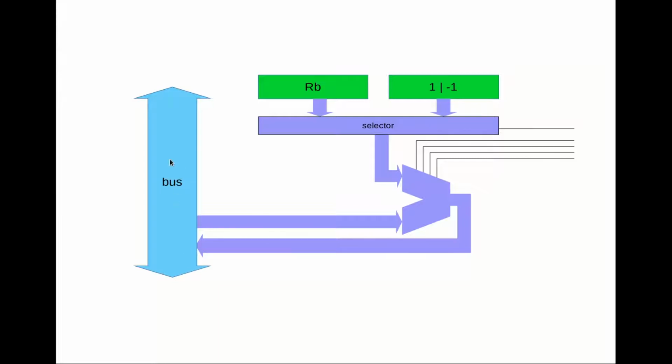That's going to cause this bus to have an inconsistent state, or worse, if two components are asserting contradictory values on a particular line of the bus, one asserting a 0 and the other asserting a 1, we're going to have a very large current flowing on that bus, and we might actually damage some of the electronics.